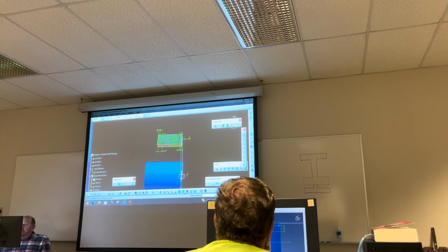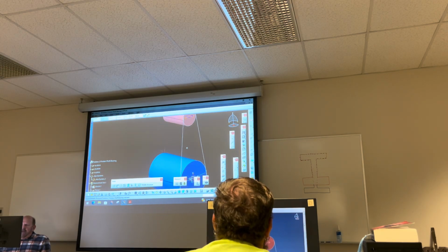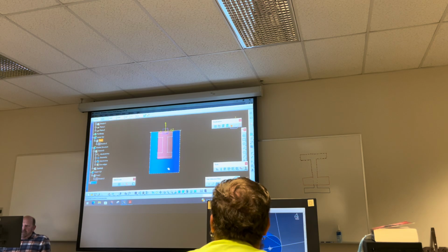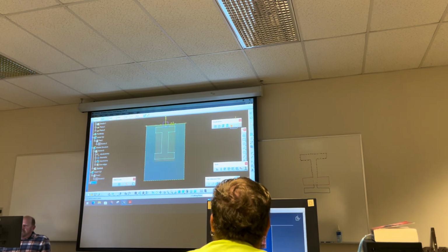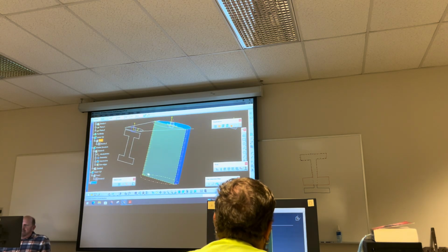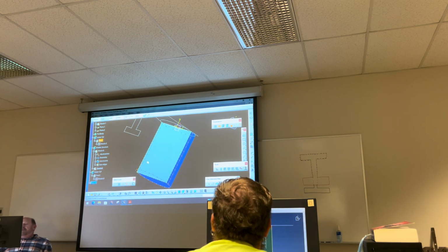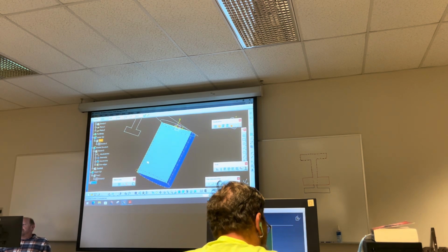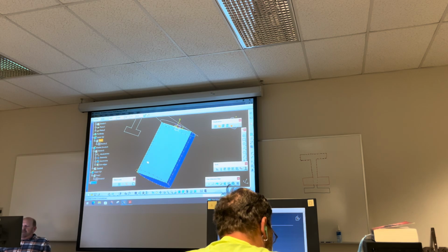Okay, so I'm gonna exit that. I'm gonna go back to, you can see the shape up here. I'm gonna make sure that I'm still in this body, and I'm gonna go into sketch 6 now. Okay, so I've already got what I need there. I will split this in half, and did you notice when I split it, when I was at the top, it cut it from my view plane? When I was in an ISO, it cut it from the bottom up. So